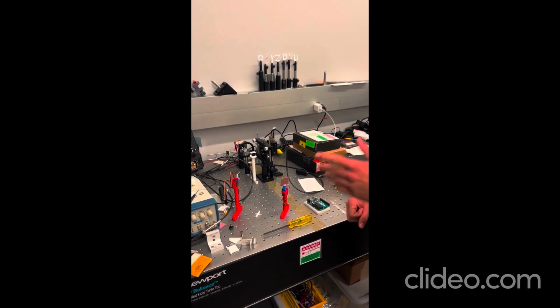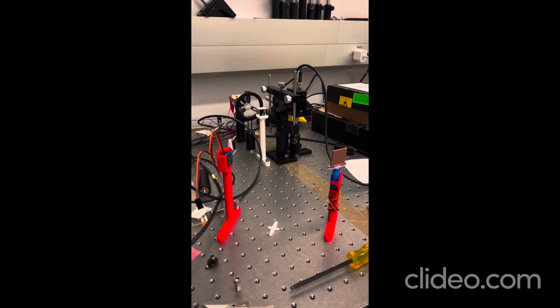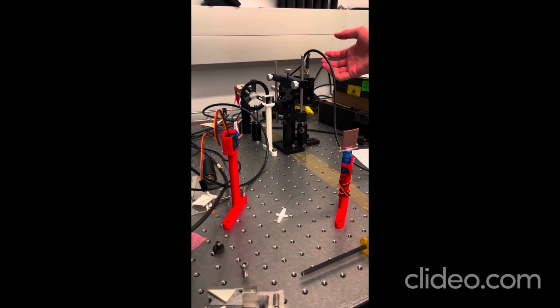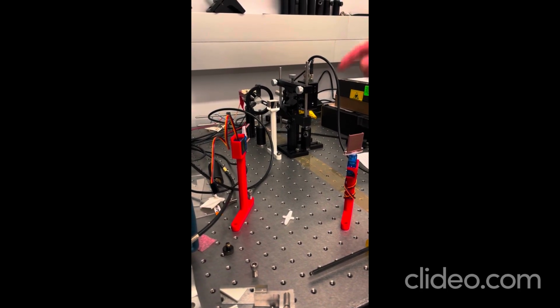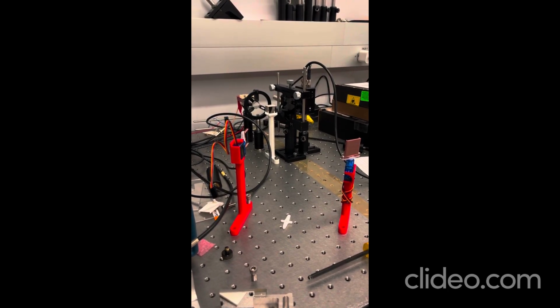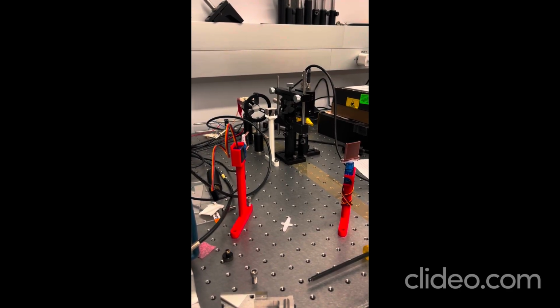Okay, so for the system alignment, we want to keep everything at a consistent 5 inches to the center of all the components. This meant raising the APD and the laser and the associated components with that. But it also meant 3D printing custom mounts for the beam splitter and 2 servos, which will be talked about more later. And right now we currently have one of these servos pointing directly back at the beam splitter to